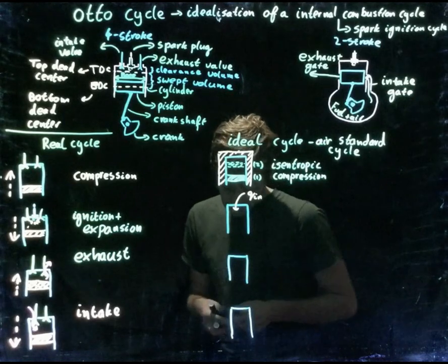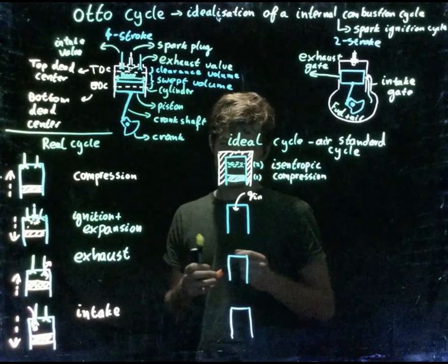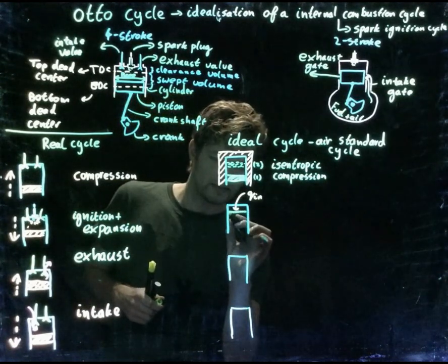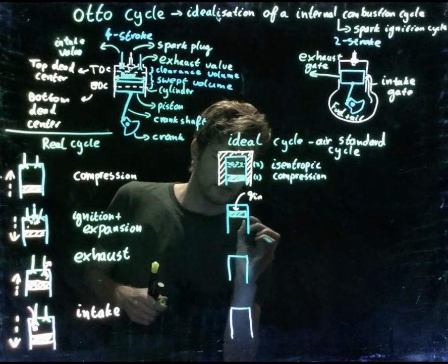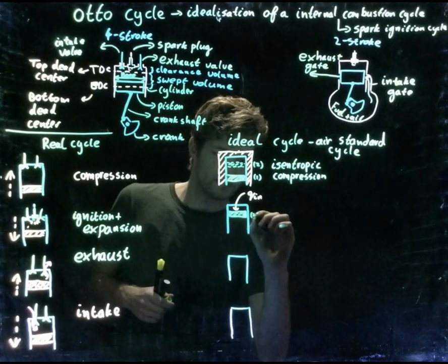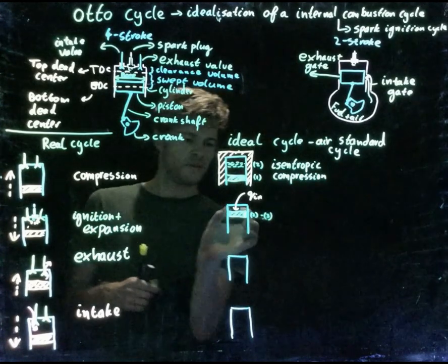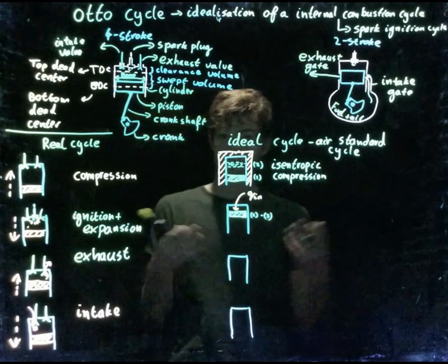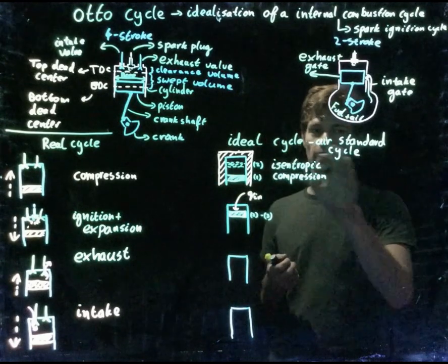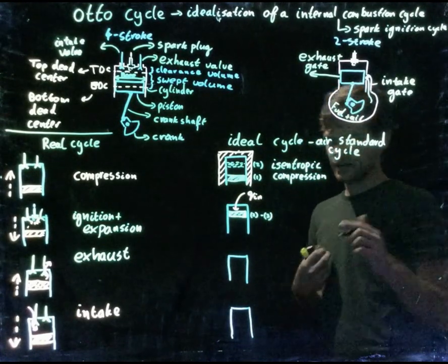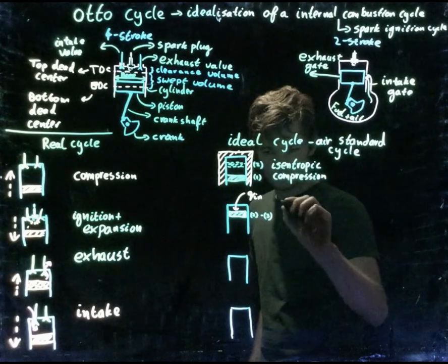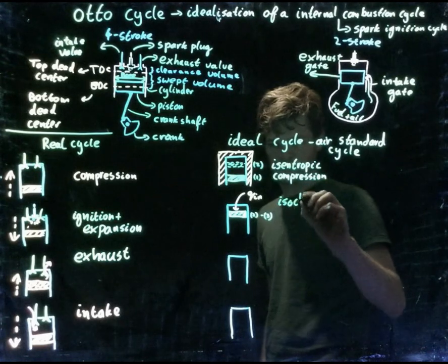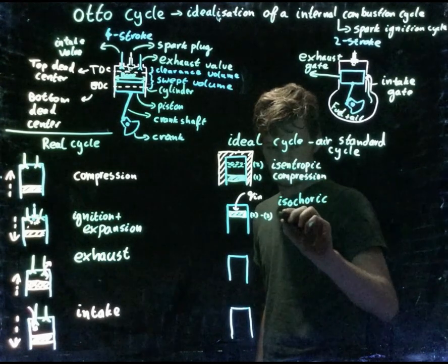And in this stage, we actually assume that the air heats up. So it's no combustion and expansion, but the air is just heating up, because we're talking about an ideal air situation. And this happens at a constant volume. So the piston doesn't move. So this is called isochoric heat addition.